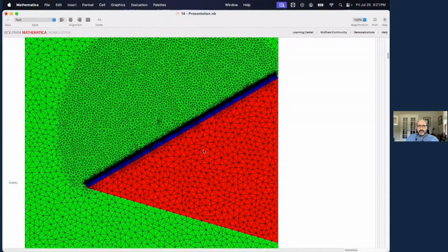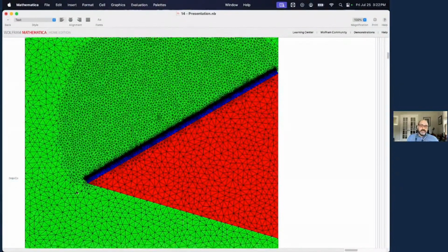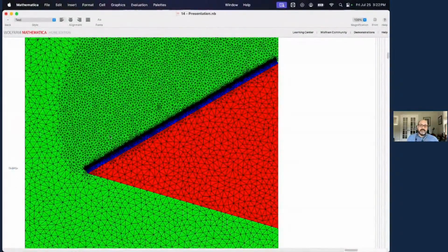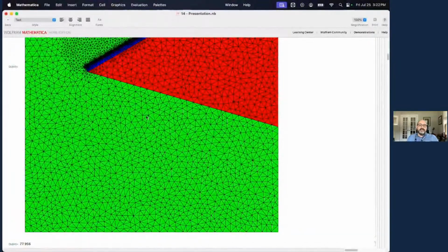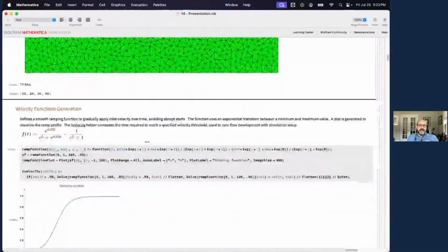Now, one of the things on this one is, as I was saying, Mathematica will solve anything. The question is how long will it take? And that's where you have to come in and say, how do I optimize my technique? You can see the mesh elements. These are coarse. These are very fine. When I get a very refined mesh on the area where the interface is, that's where the most interest is for my research. Here, you'll see later, I want to remove it from the mesh. With that said, you see the different colors represent the different characteristics of the materials.